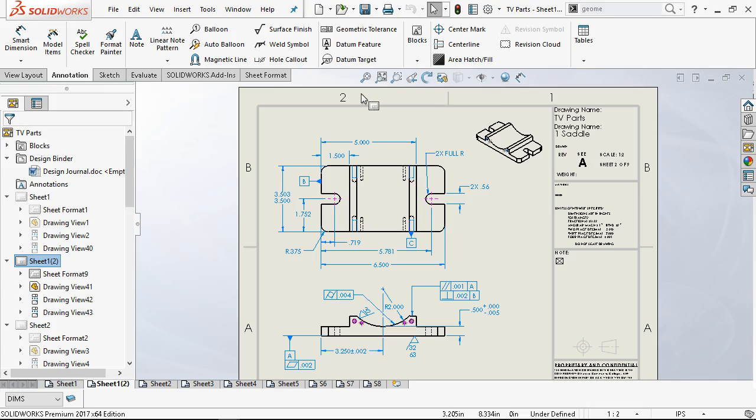Right? So we need to decide where those tolerances are going to land. And going through this, I don't want to inject any more tolerancing in this than I need. Standard tolerances for CNC, standard tolerance even for the manual milling and the grinding of the surfaces are going to, in most cases, be well within the tolerances that we need for this part, even at that order of magnitude above.